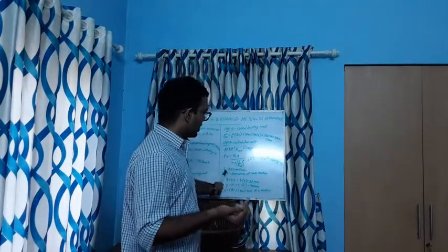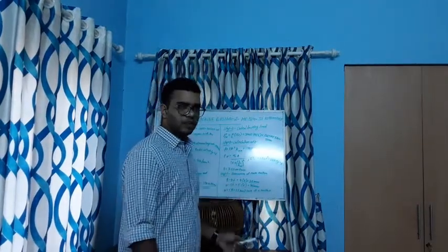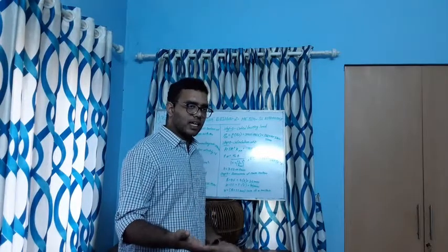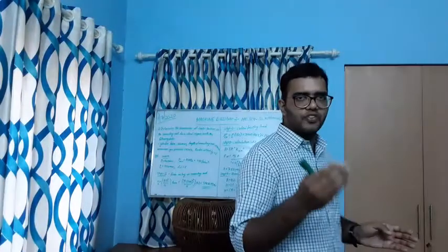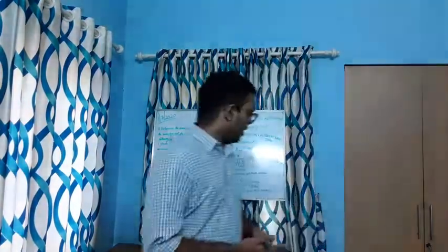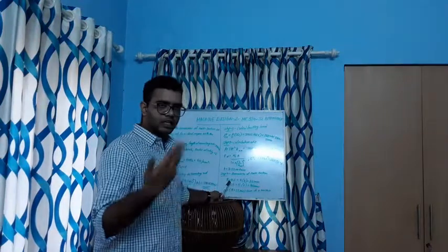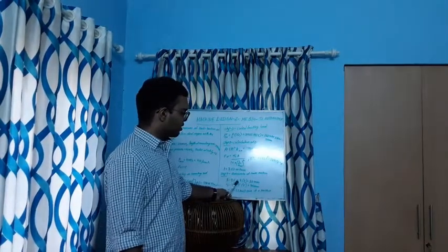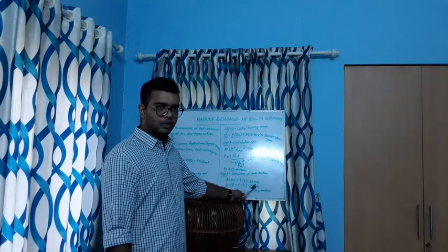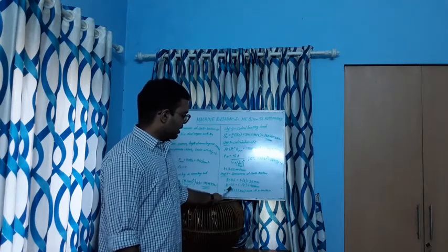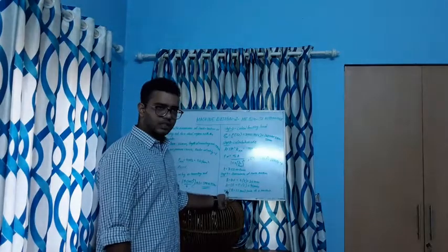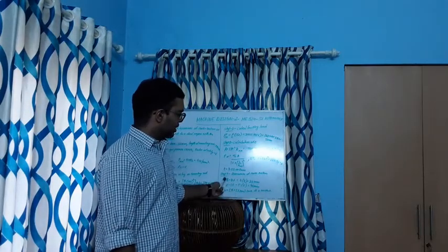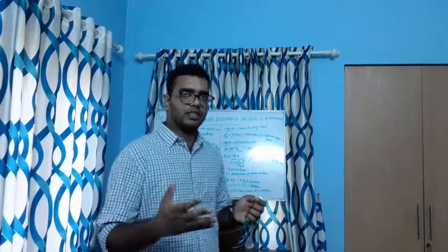We get the value of small t is equal to 7.53 and we round the value to 8 mm. That's the thickness t. Once we have found the thickness, the breadth is already in the data book: breadth is equal to 4 into t, which is 4 into 8, that is 32 mm. And height is 5 into t, that's 5 into 8, that is 40 mm. The width and the breadth are the same since it's a constant.